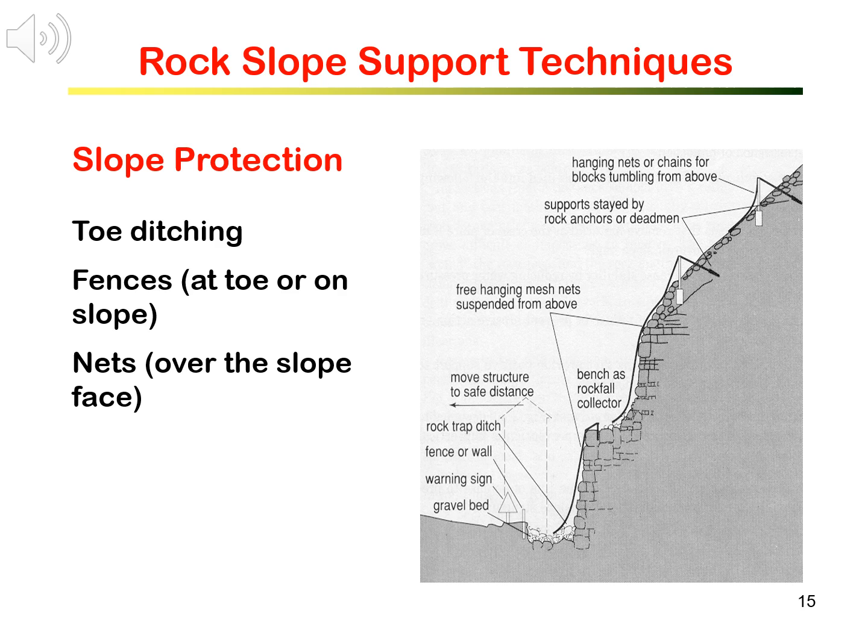Slope support measures are to stabilize the slope and to prevent the slope from failure. Slope protection measures are to protect people and the structure below the slope from slope failure. Those protection elements range from nets on the slope face, ditches at the foot of the slope, fences, and roof structures over the roads. Mostly, steel wire mesh nets are used to cover the rock slope to protect rock blocks from falling. Steel nets are anchored by rock bolts.